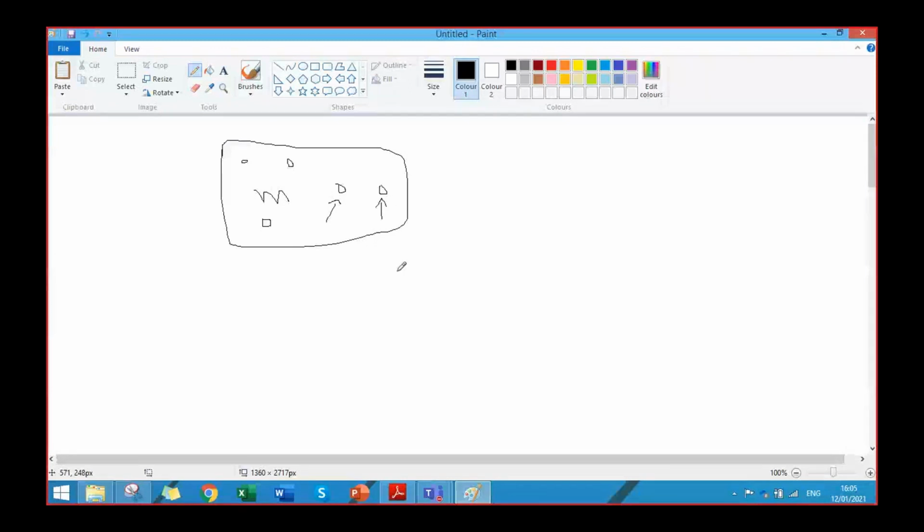So this is basically which approach? The Lagrange approach. You are tagging the mass. You are tagging specific mass. You're studying specific mass. So it means it is the Lagrange approach. But we have already studied that the Euler approach is more convenient in fluid mechanics. Why is it more convenient?